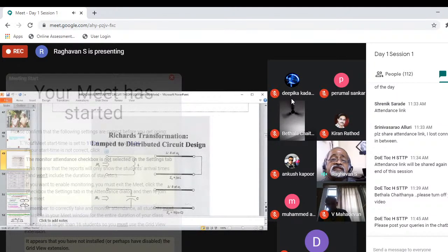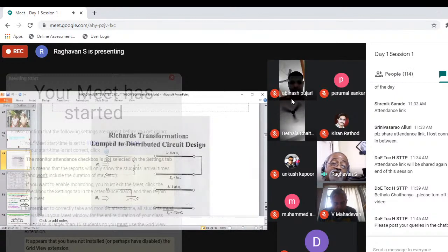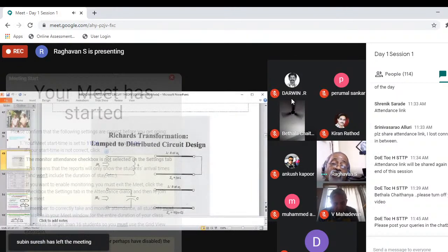And this is the Richards transformation: take a small transmission line, open it, and it will behave as a capacitor. What is small? Anything less than lambda g by 4 is small, because whatever you do after lambda g by 4, the theory will be the opposite. Plus j will become minus j. Among lengths less than lambda g by 4, lambda g by 8 serves another important purpose, because tan of that becomes 1. In any case, lambda by 8 is another popular length of transmission line. If you make it lambda g, it will hold good for any transmission line.